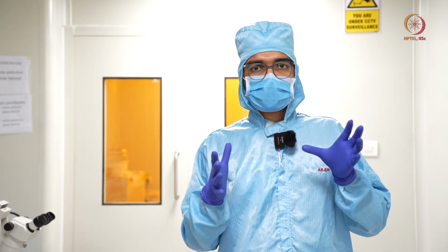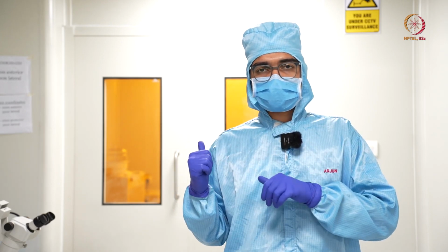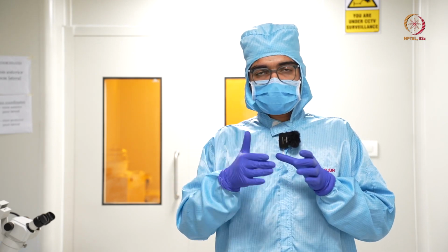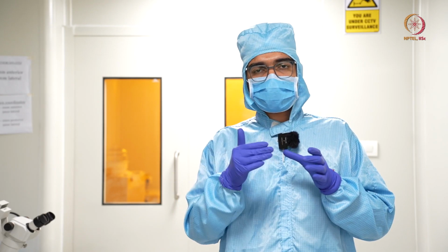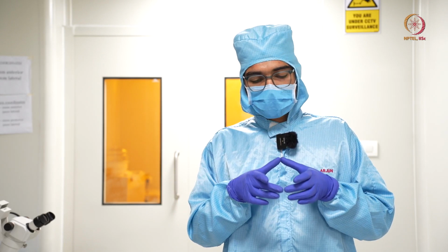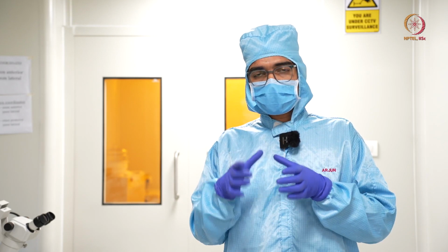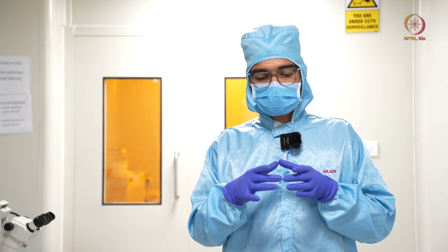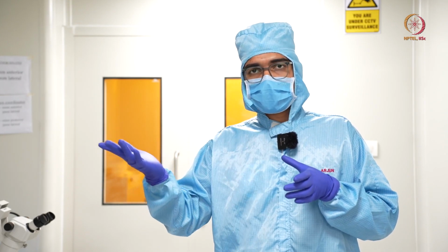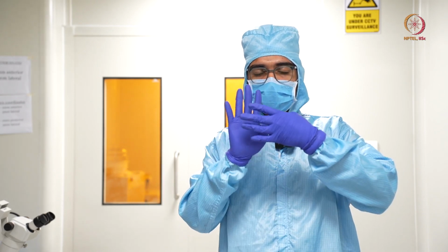Now after the pre-bake, what we have to do is we will do the lithography process. Now after pre-bake, when you do the lithography, the areas where the light falls can become soft or hard based on the property of the photoresist. When I say the photoresist becomes hard, what it means is that when you put in a solution known as developer, the photoresist that is hard remains there, and the rest of the soft photoresist will go away.